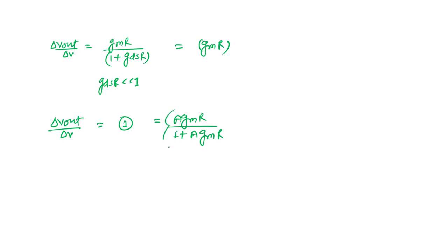Okay, so the second circuit is rejecting the supply noise in a better way. This is for circuit 2 and this is for circuit 1 in the second case. We can see it comes nearly 1. In comparison to the previous circuits, for the source follower structure, the supply noise rejection was better, but here it is a little bit far off, but even so it is better for the gain boosted structure. It is nearly 1.